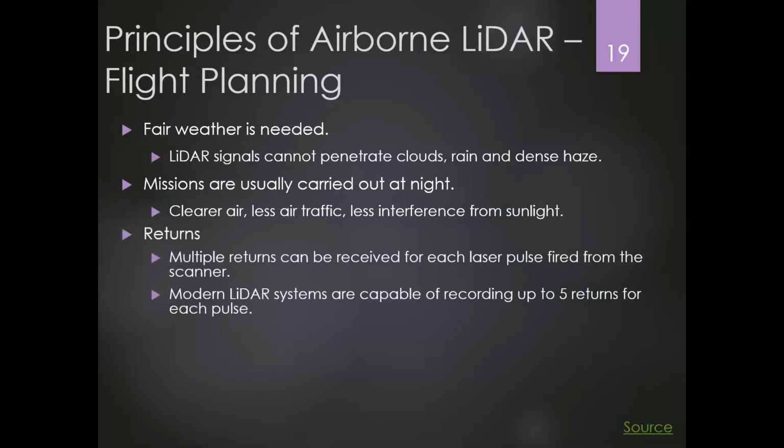Returns. Multiple returns can be received for each laser pulse fired from the sensor. I mentioned this before, right? I will provide more information later, but now just remember, for each laser pulse, there could be multiple returns. Modern LiDAR systems are capable of recording up to 5 returns for each pulse. Of course, the more returns you can have for each pulse, the more expensive your sensor is, okay?